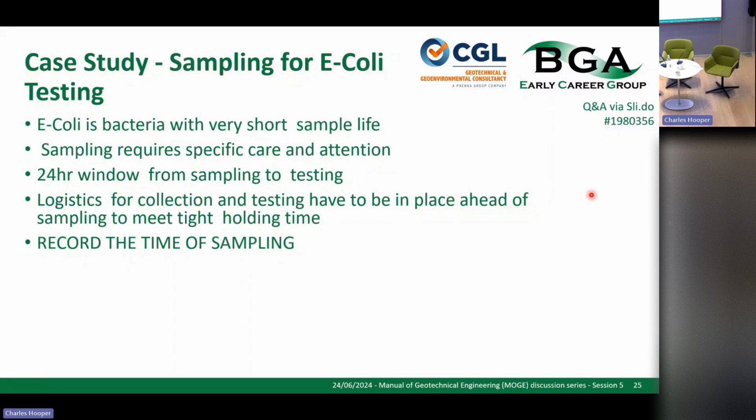It's not often that we have to go to site. We have to wash our hands, turn the tap on, leave the tap running for 2 minutes, disinfect the tap. The sampling methodology says you need to clean up the tap by putting it under a naked flame for a minute. Let's say we didn't do that. We used alcohol wipes instead, but that was an option. It did prefer us to actually put a naked flame on, unless of course it was a plastic tap.